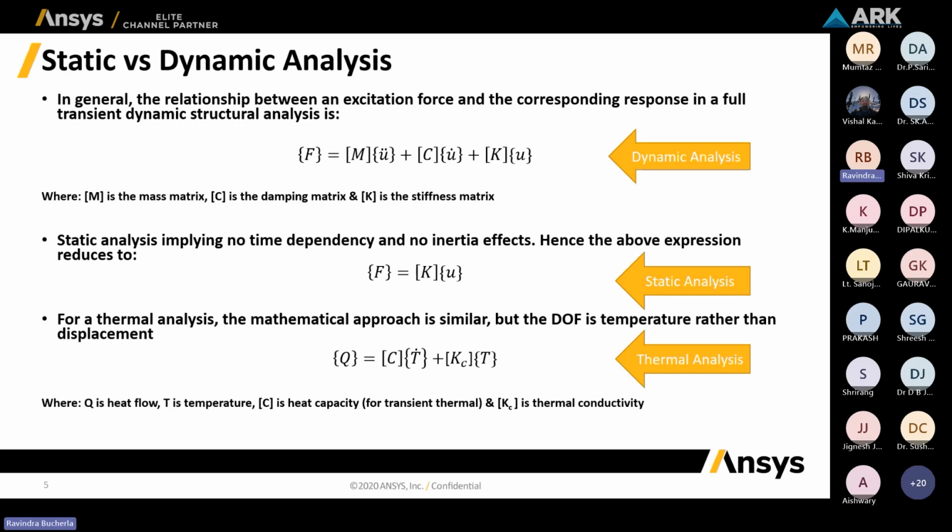Basically, whenever we solve any problem which has no dependency on time, we will generally consider it as a static analysis. And for solving the static analysis problem, this is the equation that we use: F equal to K into U. So F is the force that we are going to apply, K is the stiffness for that particular model, and U is the displacement that we will be getting because of this applied force.